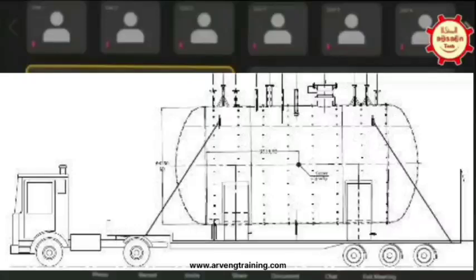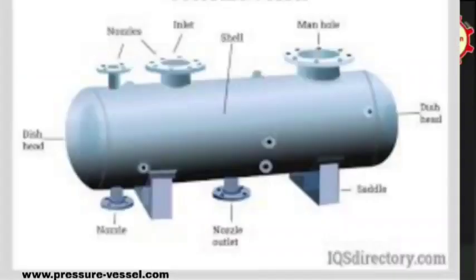There are two different cases. One is only for transportation, and one is a horizontal vessel wherein the saddles are permanently attached to the shell. I can suggest one solution with maybe 2 saddles. Out of this 30-meter stretch, where your saddle is welded, locally you can increase the thickness. That is one way of doing it. And one more is that, as you said, you can increase the number of saddles by looking at where it's sagging. On that place you can add some more.